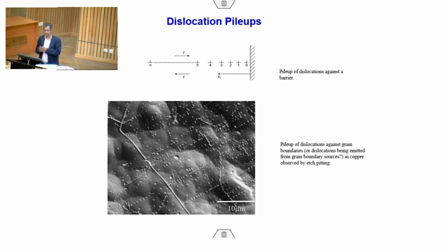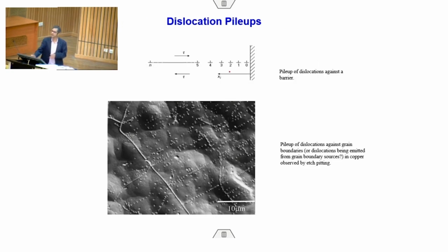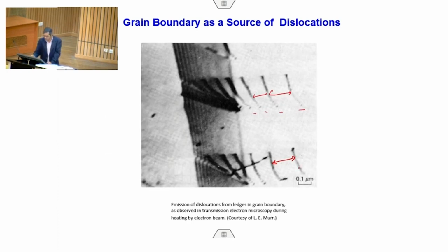Now the dislocations generated like this are moving inside the grain, correct? So, then what will happen? They will go to the next grain boundary. These dislocations which are coming will go to the next grain boundary, and then at the grain boundary they will find an obstacle. You must be thinking why? That is very simple, because grain and grain boundary structurally are different, they are not the same. Secondly, each grain is crystallographically oriented differently. The fact that this dislocation is moving on this grain means this grain is oriented in such a way that this is the slip plane, that is why they are moving.